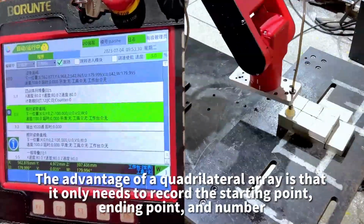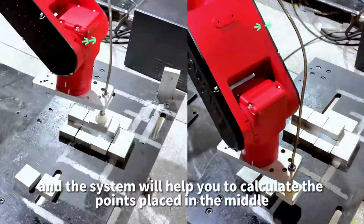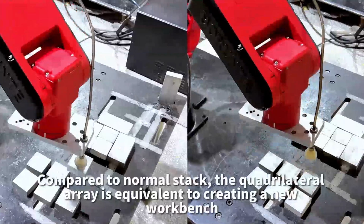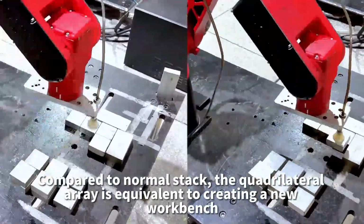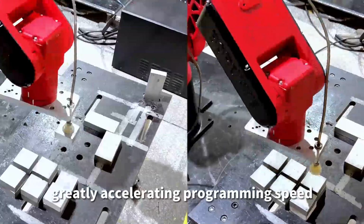The advantage of a quadrilateral array is that it only needs to record the starting point, ending point, and number, and the system will help you calculate the points placed in the middle, greatly reducing programming difficulty. Compared to normal stack, the quadrilateral array is equivalent to creating a new workbench. No need to set additional user coordinates, greatly accelerating programming speed.